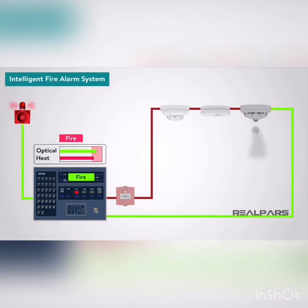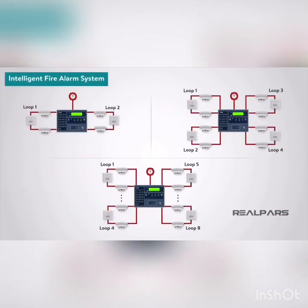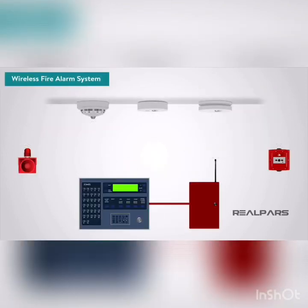Essentially, intelligent systems are far more complex and incorporate far more facilities than conventional or addressable systems. Their primary purpose is to help prevent the occurrence of false alarms. Intelligent fire alarm systems are available in 2, 4, and 8-loop versions, which means large premises can be monitored from one single panel.